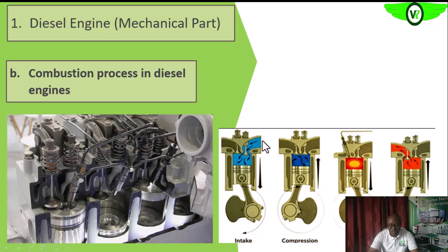So since the pressure outside is higher, air will flow into the chamber. Okay, so that is the intake stroke. Then once the piston has been driven to the bottom dead center, when that particular lobe, that particular journal of the crankshaft is returning up, you see that the piston will start driving up.